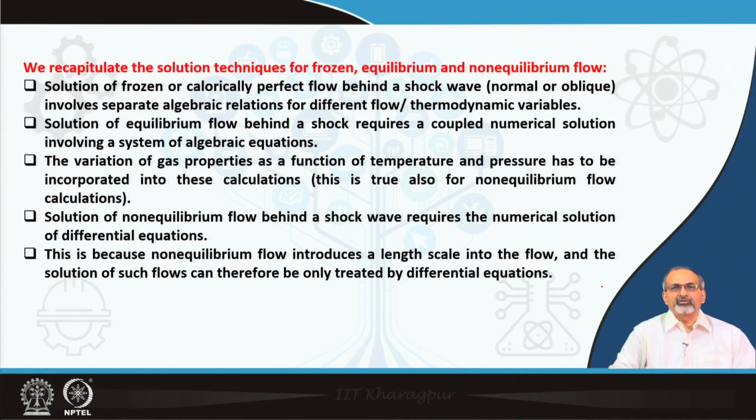And we recapitulate the solution techniques for frozen, equilibrium and non-equilibrium flow. Solution of frozen flow is based on algebraic relations. Solution of equilibrium flow involves a numerical solution where we couple all the equations and we incorporate the variation of gas properties as a function of temperature and pressure. Solution of non-equilibrium flow involves solution of differential equations, and that is how a length scale is introduced into the flow.